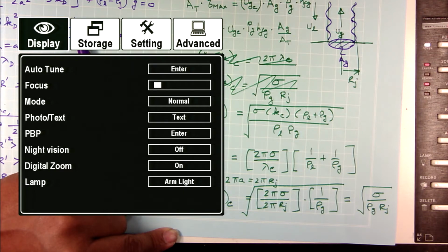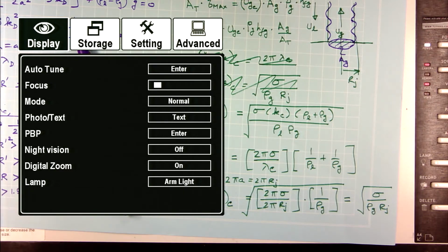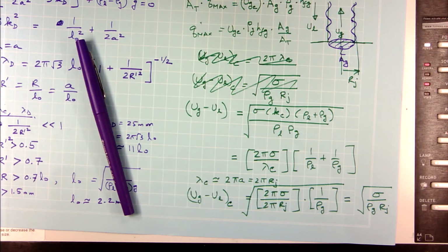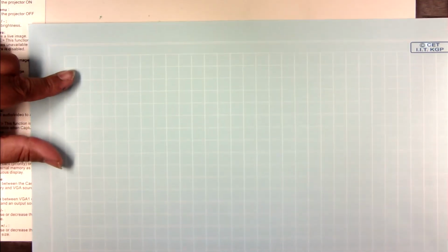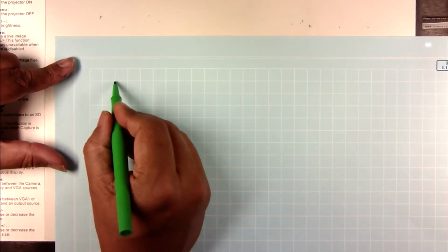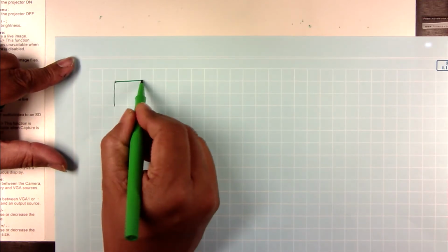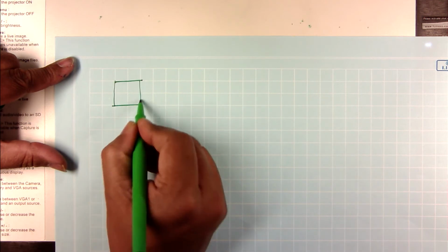Now, Zuber, when he was deriving this equation, made an assumption. The assumption he made was that during critical heat flux I form all these jets, the columns, right. So he assumed that these jets were located in a sort of square grid.